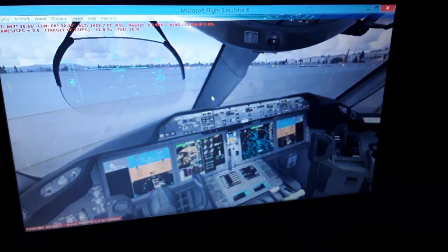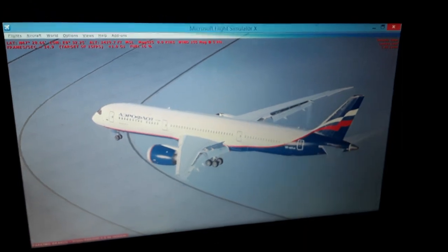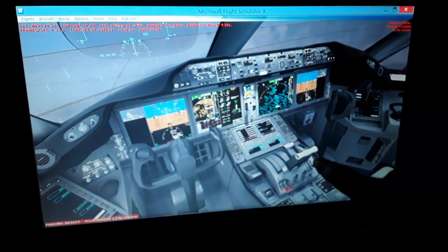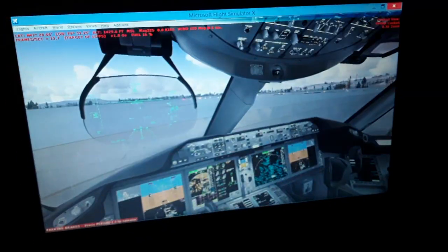I think I will have to continue now with the rest of the systems. I will explain to you about the navigation display, how we input the data of the aircraft, the takeoff gross weight, that includes the empty weight plus the passengers plus the cargo plus the fuel on board, the left and right wing fuel tanks, the center tank. This calculates the center of gravity of the aircraft, the mean aerodynamic chord position of the forward wings, and the horizontal trim stabilizer. We use the flaps for takeoff, like 15 degrees of flaps. You can see I have extended the flaps here also. The wings are down.